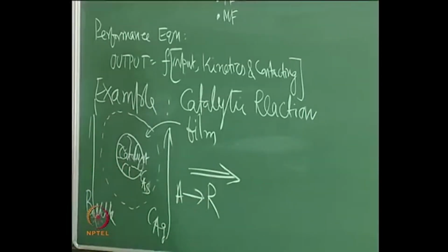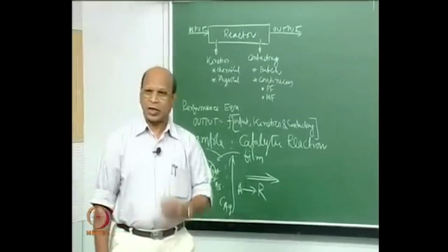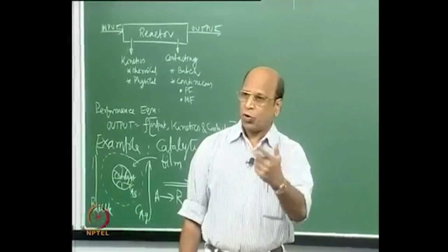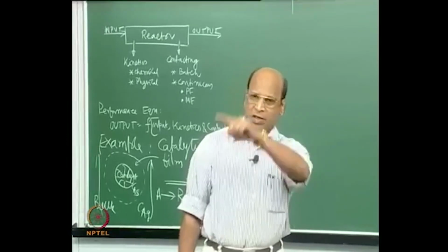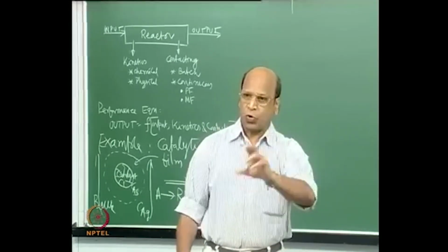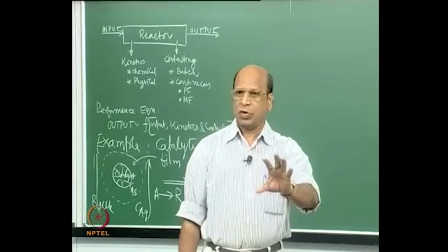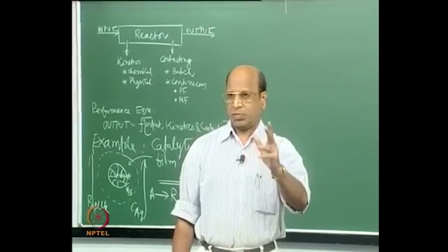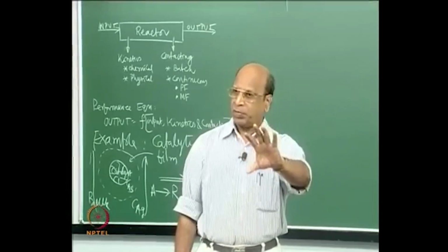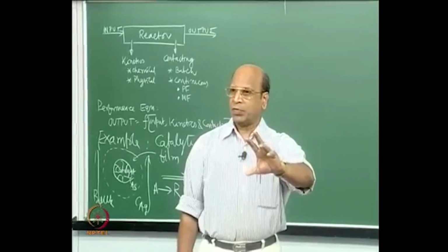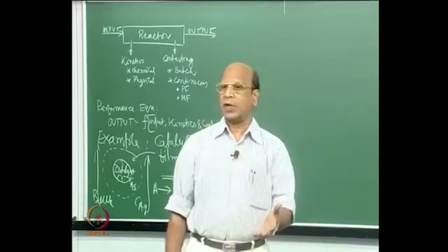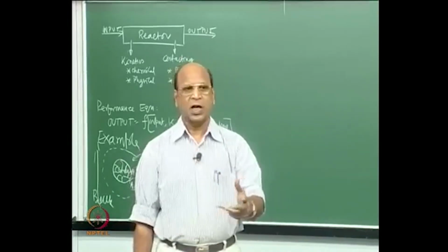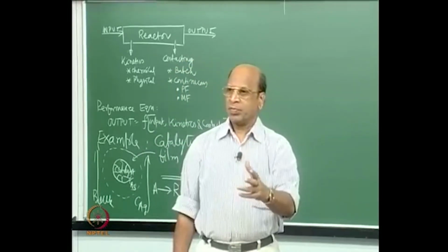So, now how many actual steps do I have? 2. What are the steps now? Yeah, mass transfer. We do not say that one as normally diffusion, because around the film or through the film convective flow also will be there around that. That is why we say mass transfer, and you know the difference between mass transfer and diffusion. Diffusion is purely by molecular phenomena, only by concentration difference, whereas in mass transfer we have convection and diffusion together.